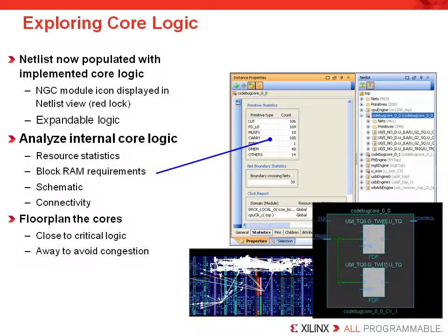The size of each debug core can be easily found with the PlanAhead flow, but also with the other flows. Since the cores are added as netlists, given the file extension of NGC, they can be selected and their size determined easily. This is important because the amount of resources will vary by the number of match units you are sampling.